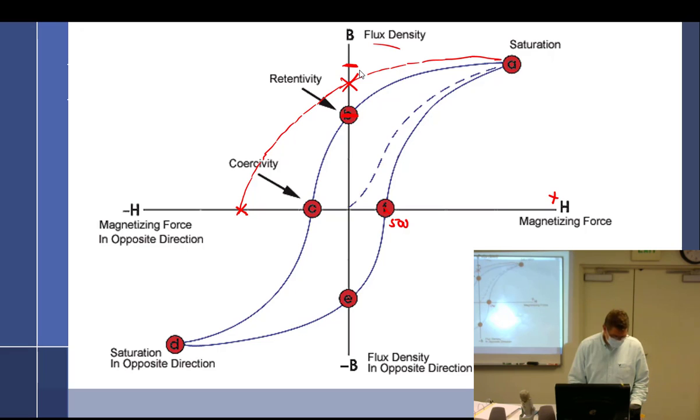Okay, so A. The force is removed and the remaining magnetism decreases to point B right there. And then when the magnetizing force is applied in the opposite direction, the process is reversed in the opposite direction. Magnetizing force is applied C and the part reaches the saturation point D. When the force C is removed, the part has residual magnetism E.